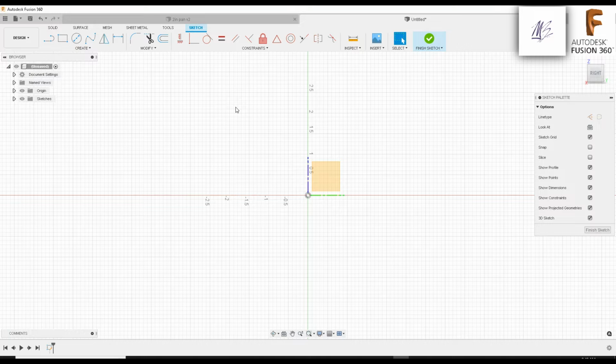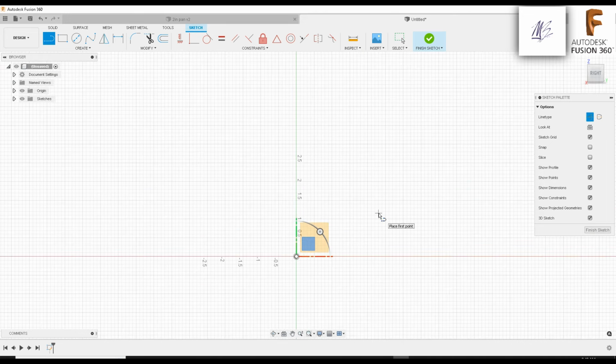Now we need to design, well, we're going to put in constraints, right? Like I said, I have the rough measurements for the pot itself. The depth of the pot is 4.5 inches deep. The thickness of it is 1/8 of an inch. The diameter of the pot itself is 9 3/4 inches. So let's put in some constraints. Left click line, go over to sketch palette, left click construction. We want construction lines for now because we're not putting in any definite segments yet.